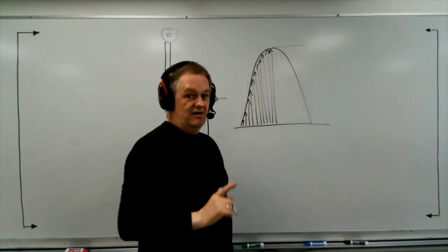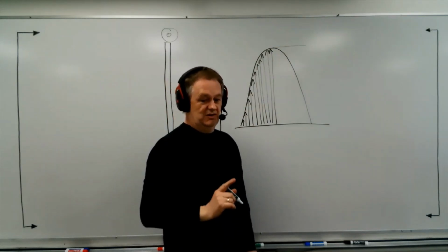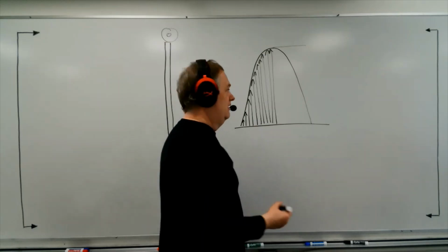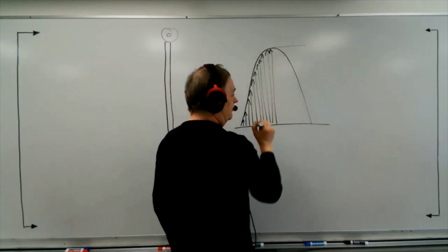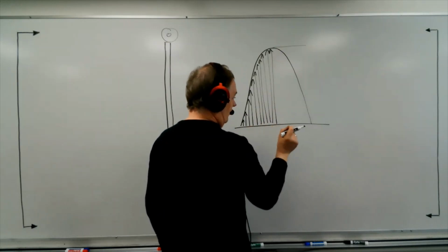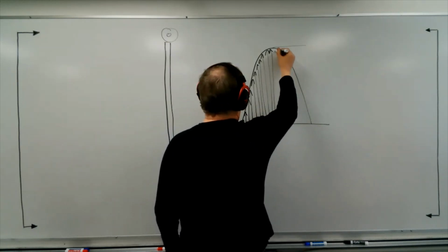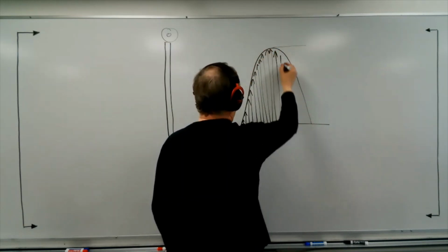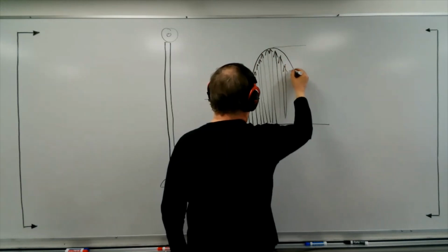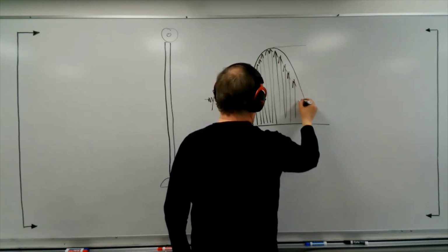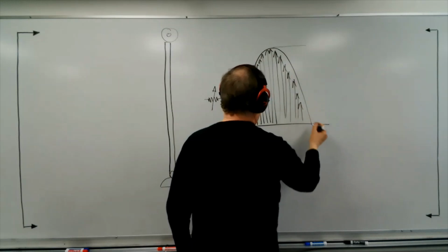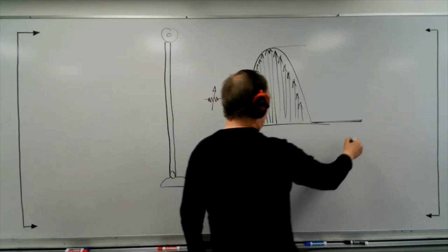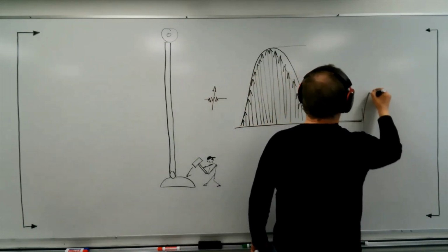If it is not enough current to ring the bell, or in our case, to fire the SCR, then the SCR is going to remain unfired. In other words, it will still be open, and the current during the second half of this 180 degrees is just going to fall. And you won't get another chance. You won't get another chance to try even until after the negative alternation has gone by, and then you start on the next cycle, and the voltage will start to go up again.